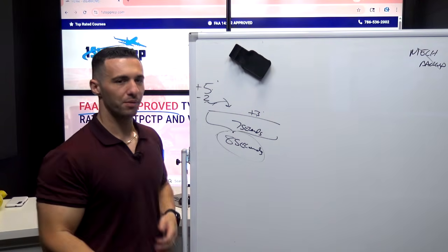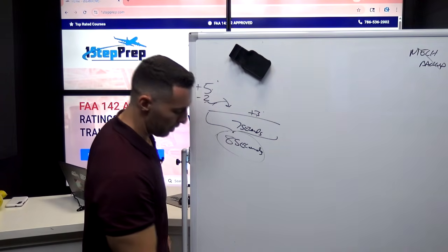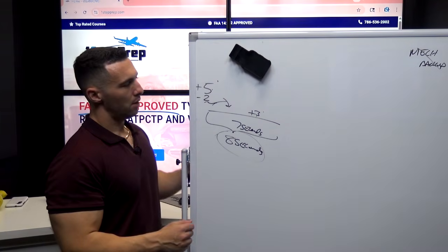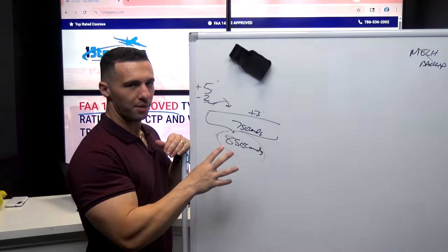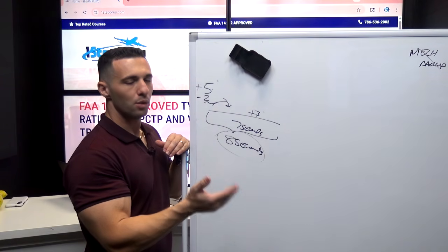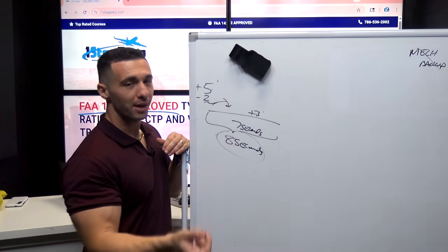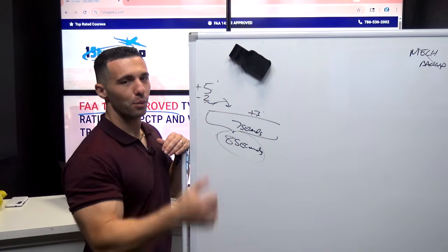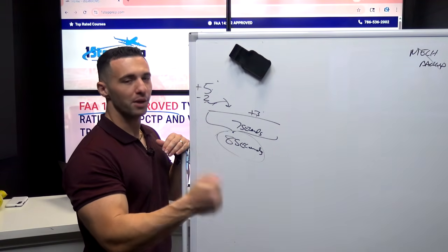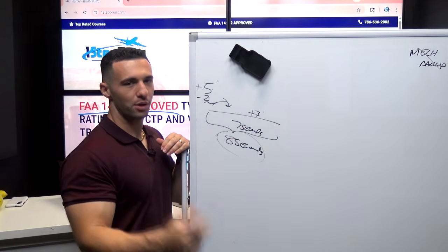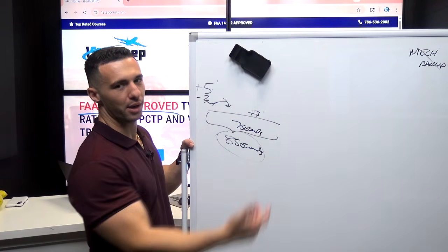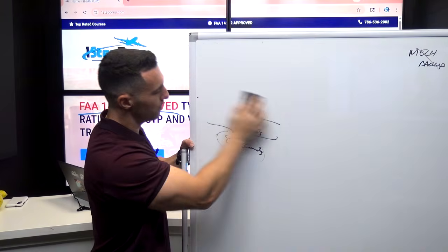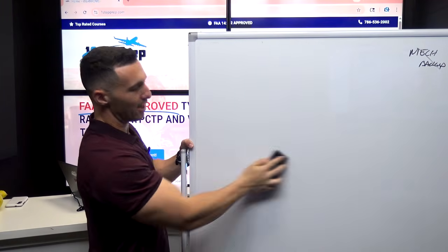That's kind of the recap of the modes. All these modes are really only available in normal law. And in alternate law, you don't have this flare mode, which is why when you put the gear down, you go to direct. So that we're not landing in G-load, but we're landing in a direct relationship, which models more closely to what you've always had in any other airplane that is not an Airbus product, so that you can land more accurately, or at least have it feel more natural.